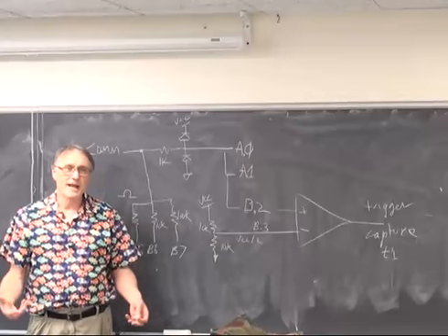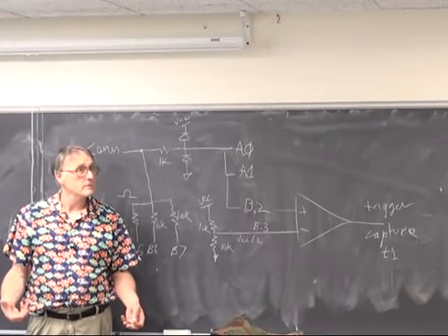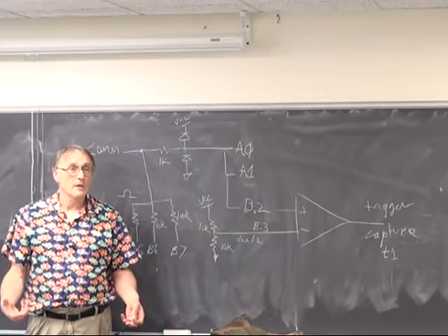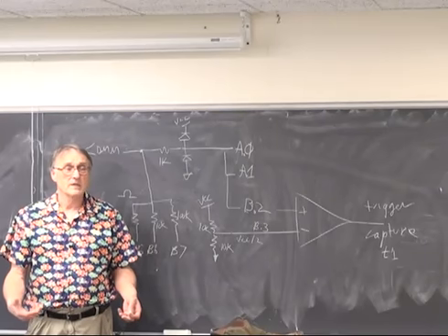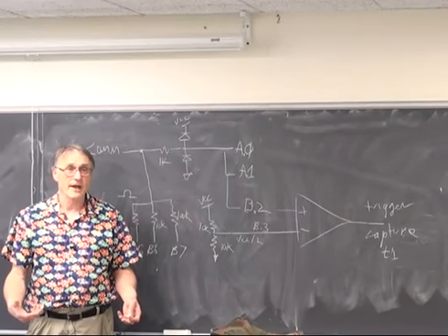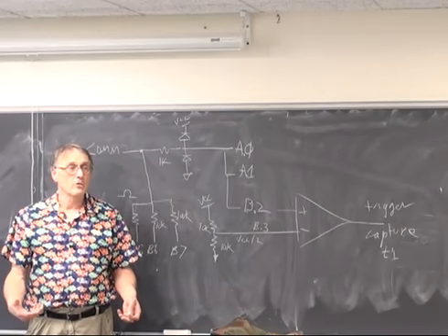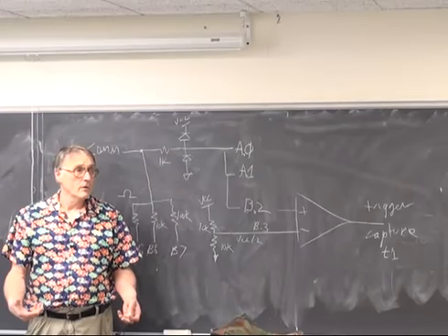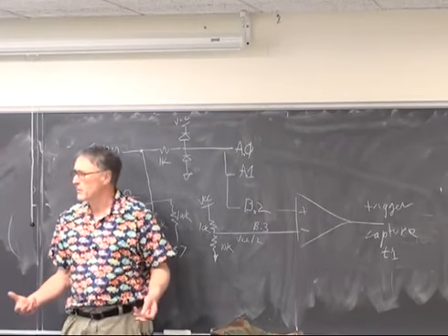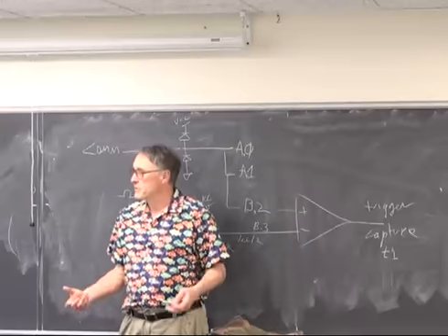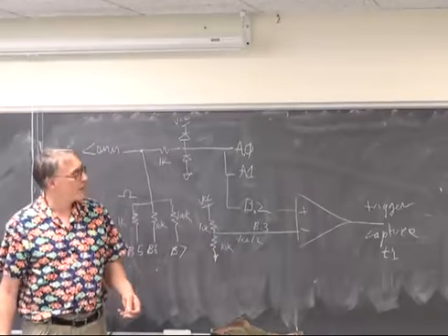If you want to get 1% accuracy, you have to count at least 100 counts. Right? On the other hand, if you count more than 16 bits worth, 64,000, you overflow. And so you have a limited dynamic range. It's a fairly large dynamic range of frequency, but you probably will need to auto-scale that.